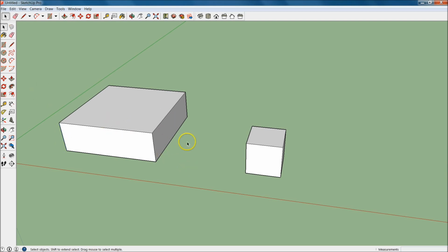But if I wanted to just have a little bit in there, if I start from the bottom right and move up, you'll see that my box is this dash line. The marquee is this dash line. And what that'll do is select everything that any piece of that component or part touches. So if I let go right here, you'll see that this surface was fully selected even though the whole surface wasn't within that marquee. Also, these lines coming out right here weren't fully in the marquee, but it still selected them because part of them was in there. So again, if I click anywhere, it'll just deselect.